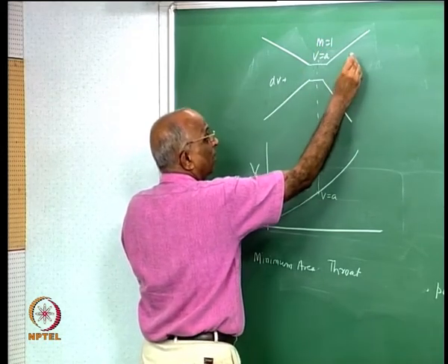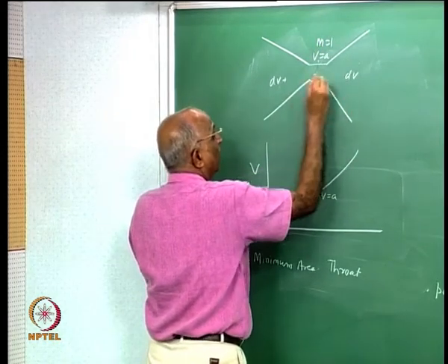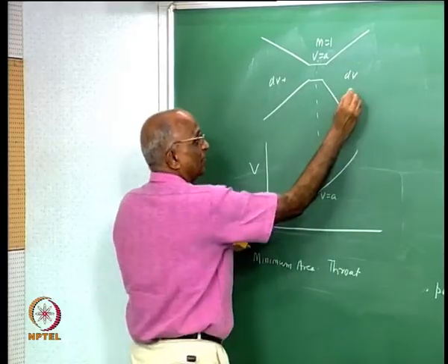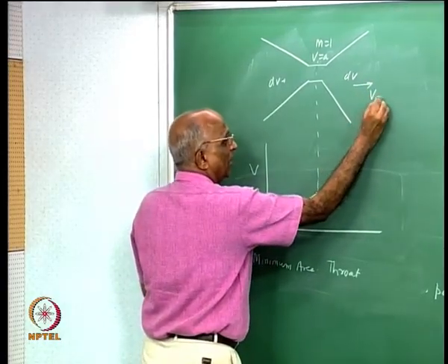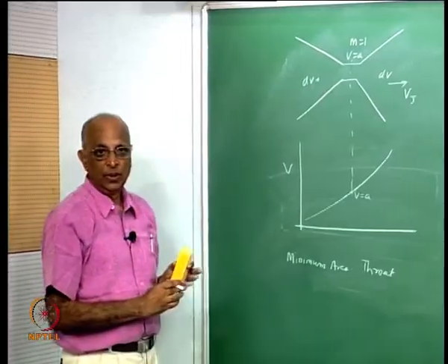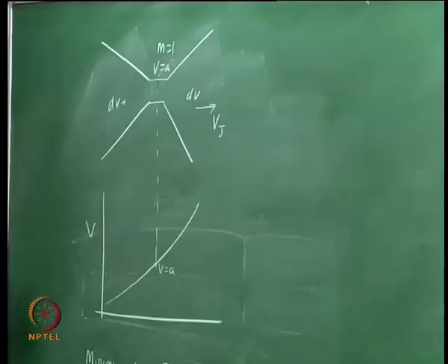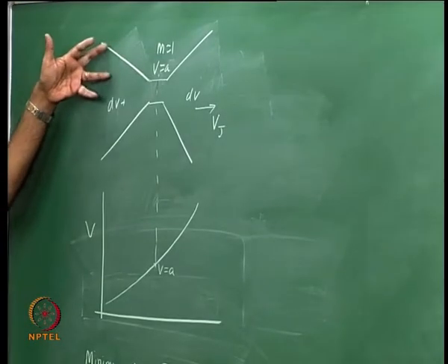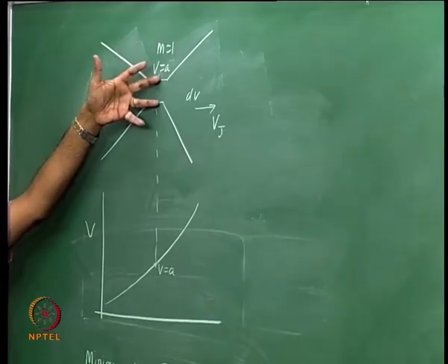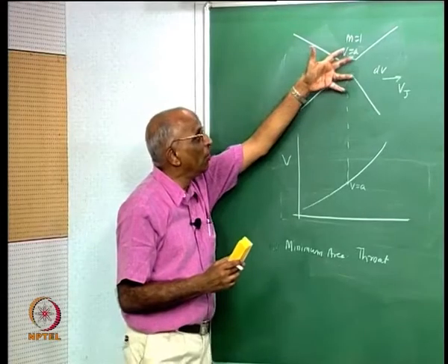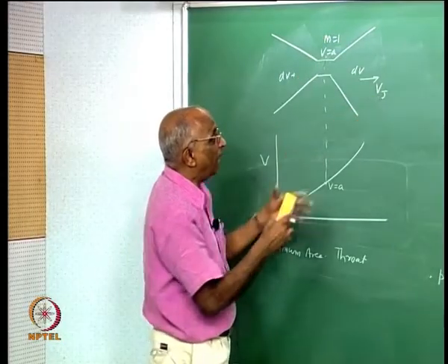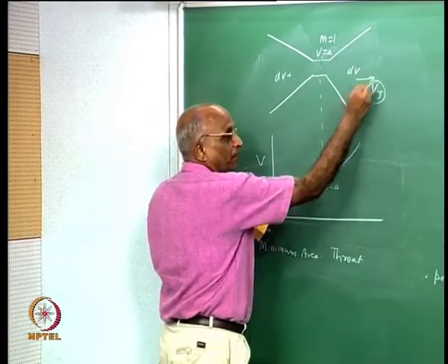Thereafter the Mach number is greater than 1 and the flow velocity increases, and therefore I can have a high value of jet velocity. Therefore, the configuration of the vent should be a convergent section followed by a constant section which I call a throat, followed by a divergent section, if I have to get a high value of Vj.